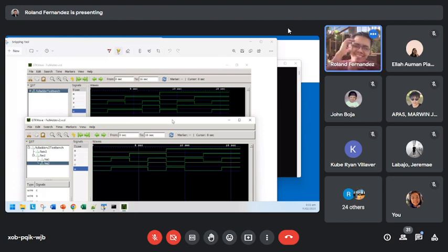It's the same. Take note, this is a different implementation because we use a previously created half adder in our design for the full adder. This is what we call bottom to top, using the smaller components in the next design. But the drawback is that we need to put it in the code again.